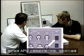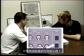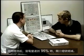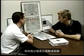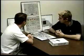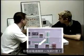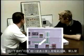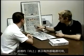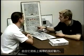APU. You've selected the APU master switch to on, and you selected the start switch to on. When do you get the avail light? The avail light comes on, and the on light goes out at 95%, and the avail light indicates that either electrics or pneumatics from the APU is available. How does this avail light differ from the avail light that you find on the external power switch? Well, the avail light down here just means that either electrics or pneumatics are available. Up here means that external electrical power is available, and it's good power to be taken on the ship.